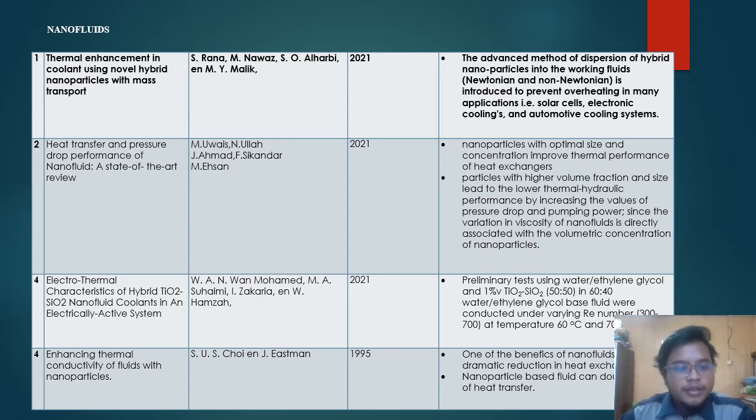The fourth one is enhancing thermal conductivity of fluid with nanoparticles. The finding is that one of the benefits of nanofluid is that the size of the heat exchanger will be dramatically reduced. Nanoparticle-based fluid can double the rate of heat transfer.